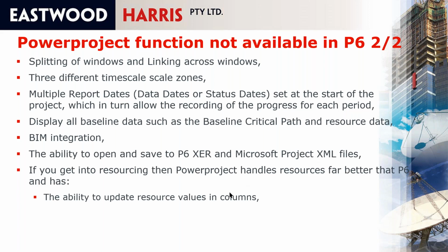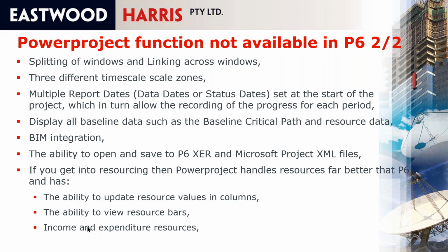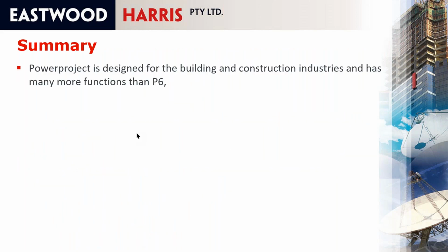If you get into resourcing, then Powerproject handles resources far better than P6. It's got the ability to update resource columns, values in columns, the ability to view resource bars. It has income and expenditure resources, and P6 and Project don't understand the difference, so you can create a resource and call it income or expenditure and work out the cost of financing your project, and it has exceptional histogram graphics.